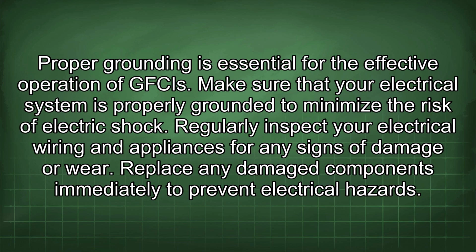Proper grounding is essential for the effective operation of GFCIs. Make sure that your electrical system is properly grounded to minimize the risk of electric shock. Regularly inspect your electrical wiring and appliances for any signs of damage or wear. Replace any damaged components immediately to prevent electrical hazards.